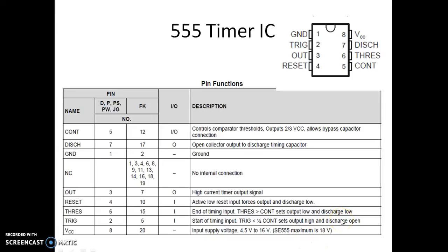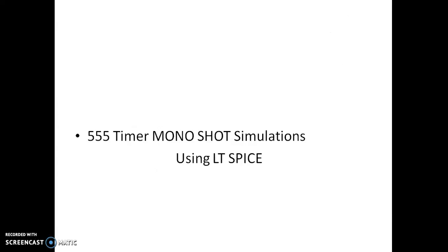Discharge open means the capacitor starts charging. VCC is pin number 8, the input power supply, and it can vary from 4.5 to 16 volts. So it is not only 5 volts, you can apply voltage up to 16 volts, that is 4.5 to 16.